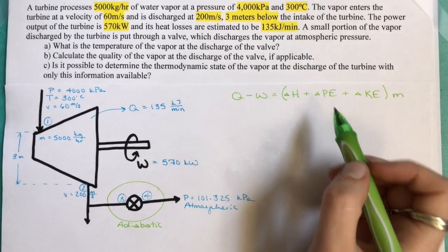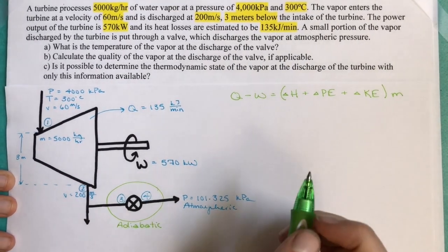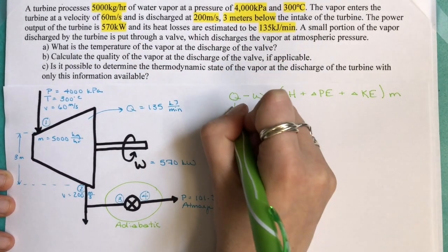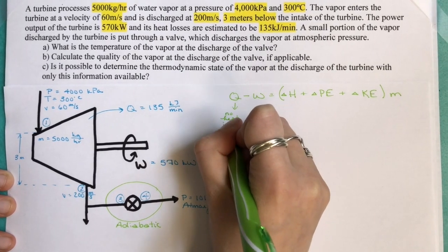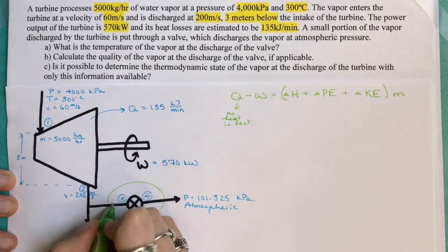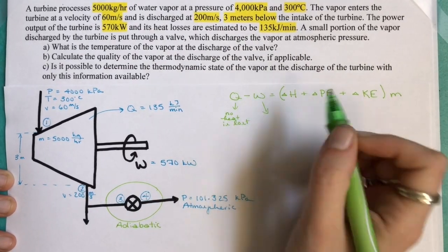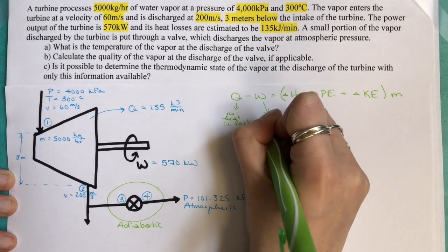Now let's think about this equation with our adiabatic valve. Because the problem didn't say anything, we can assume that no heat is lost with the processes of this valve. We also know that in the valve, there are no moving parts, so there won't be a change in work either. No work.